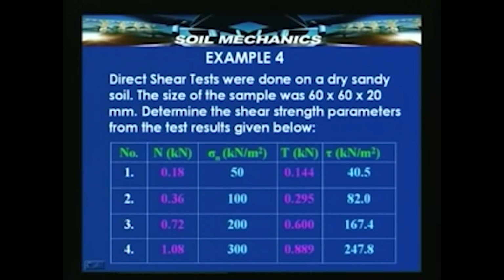Direct shear tests are usually conducted as drained tests. The reason is it is very difficult to prevent drainage in them, as you will see a little later, and we therefore usually conduct direct shear tests on sandy soils or cohesionless soils. The reason is these soils are rapidly draining, and therefore the drainage condition becomes irrelevant as long as drainage is permitted.